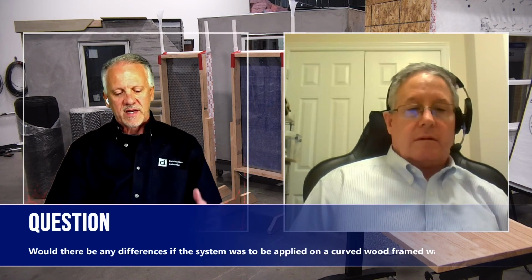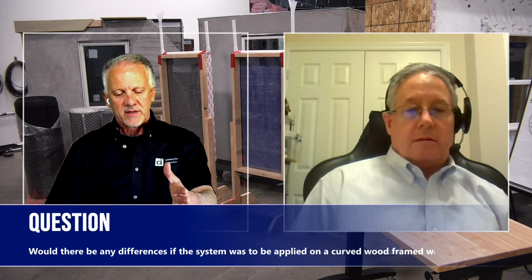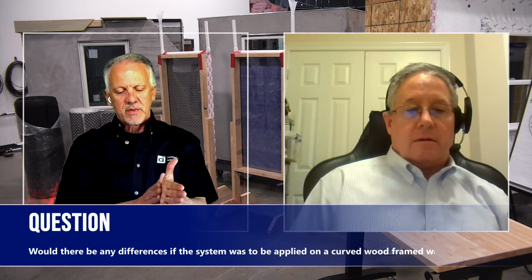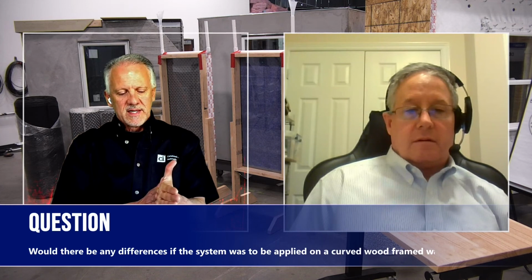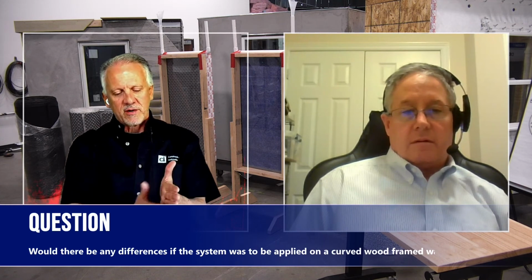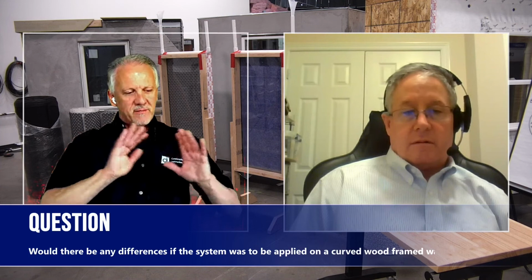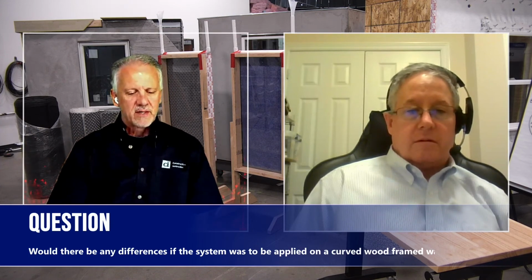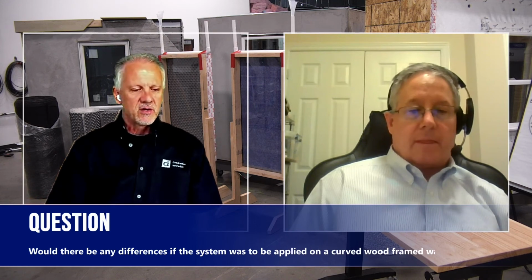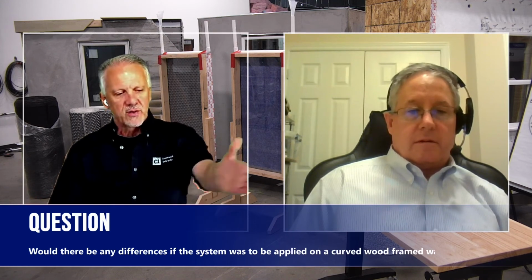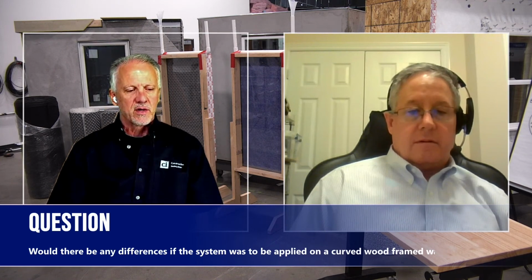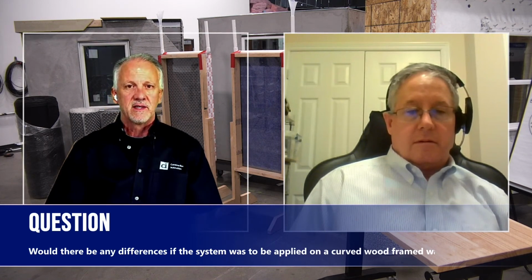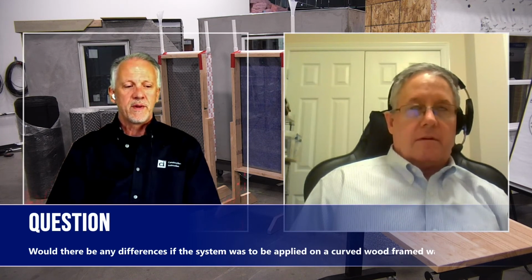So I would sure advocate that if we have the weather protection layers on the sheathing interface, which is usually layers of plywood for curves, then the weather protection layer is on, then the stone and lath goes on very nicely because it follows the curve beautifully. You would then scratch and finish your layers, whether you did a brown and finish or just sometimes we see scratch and finish, just 2-layer. But in those applications, you could do that straight on the stone and lath because it would curve so nicely and you wouldn't have to try to make the metal go around the corner. So I think that's what they're asking. I think that's a nice way of doing that, and the curve would be well done.